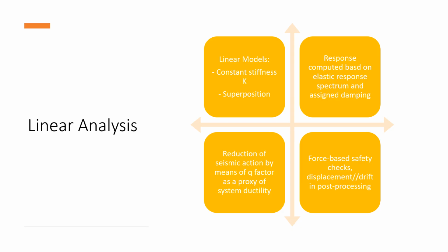And then there is this q factor, which is a factor allowing for the reduction of the seismic action, and it is something that is a proxy of the system ductility and its effect in producing an equivalent reduction of the forces.